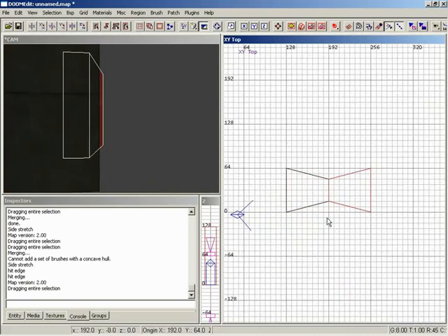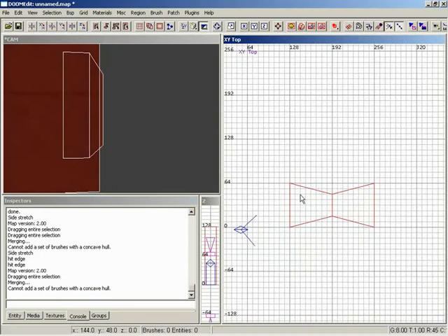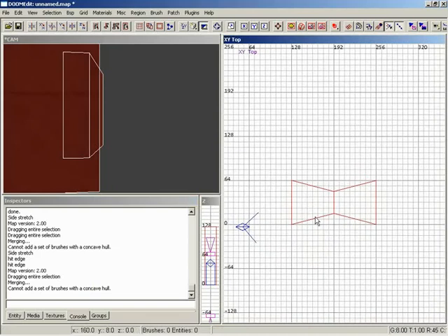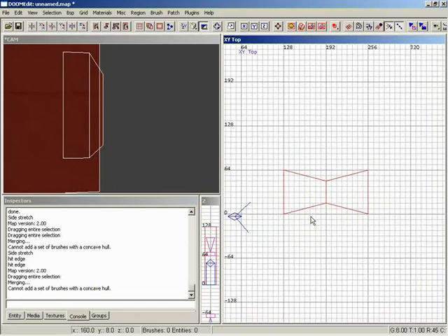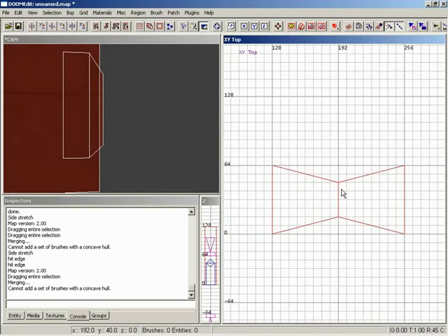Looks like an interesting shape, and you'd kind of sort of think you could merge it. I mean, it would look like one brush if you had it both selected, but if we try to merge, what happens? Must not be concave. So exactly why isn't this concave? Well, as Buzz said earlier, you can think of concave as some object where the hull dents in on itself at some point. But an actual test we can do to see if the brush is actually going back in on itself would be to draw a line through the shape.